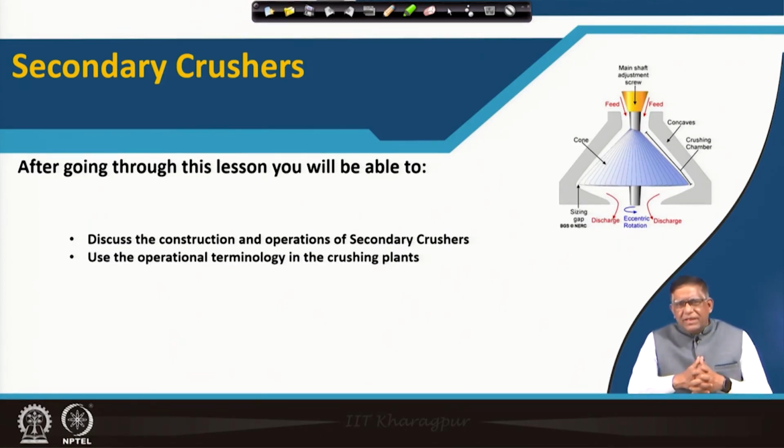Secondary crushers are needed because when you get a very big rock, you directly cannot get the very fines in one stage. So, they will have to be crushed step by step. At some stage we are doing, say, 1:10, reducing size from 10 to 1, from 6 to 1, like that. In secondary crushing, we take the material crushed in the first stage and put it in here. From there it can go to tertiary crushing, and from there to milling or grinding for making fine particles.